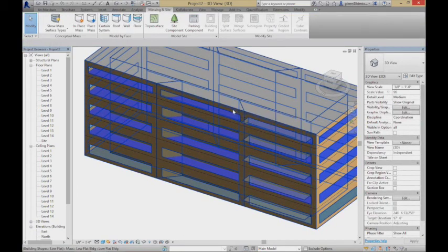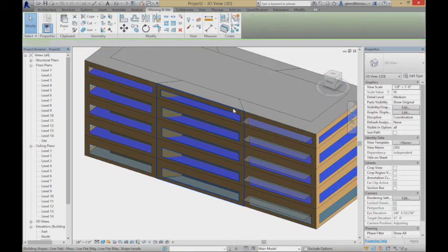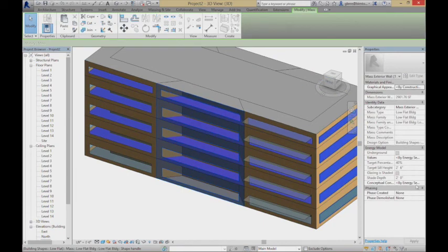I might also, just on the south side, change the glazing percentage. So for example here, as opposed to having all these little windows, I could go through and say, go ahead and make it 80% glazing, but then counteract the problem of all that glazing by making sure there's a big shade on there.